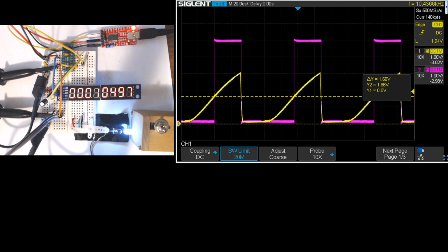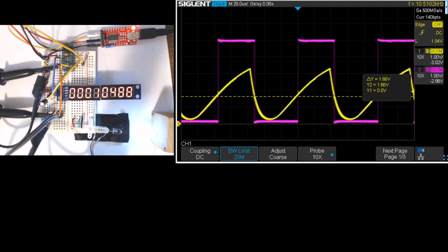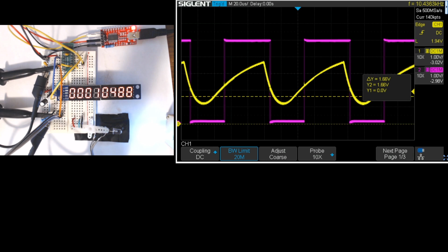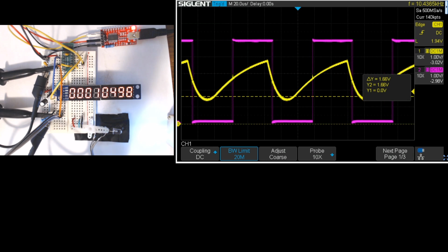So now if I move the flashlight around, I can make this curve move, and the threshold will have to be recalculated. And we can see if the count remains accurate. So if I move it back like this, then it looks like the counts are still accurate on both the oscilloscope and the ATtiny. But now I'll show you the new threshold. It'll be this point here where those curves intersect. So now Y2 is about 2.72.